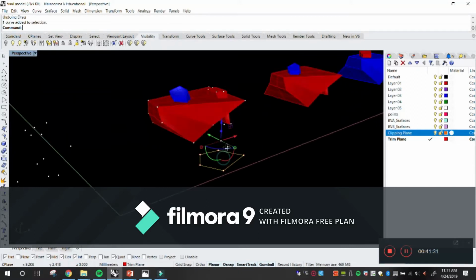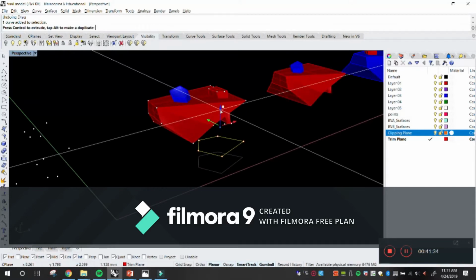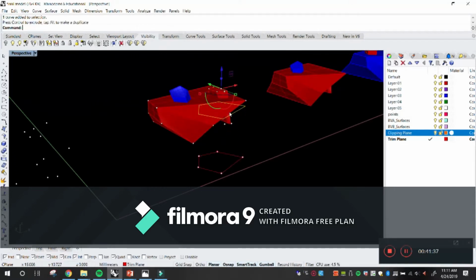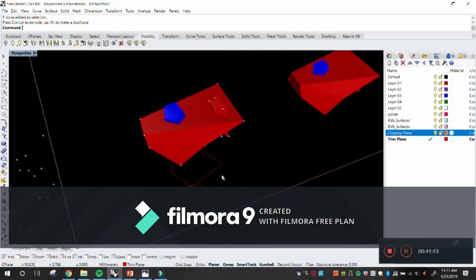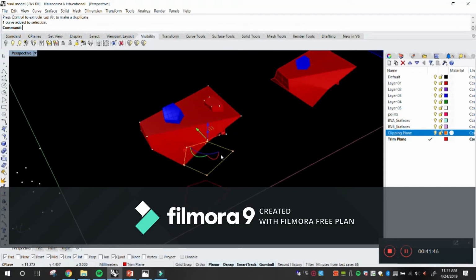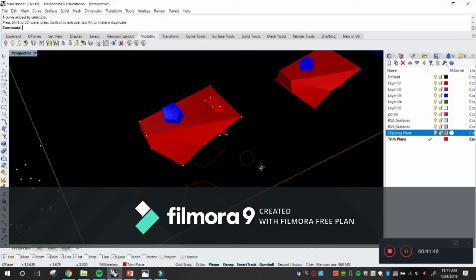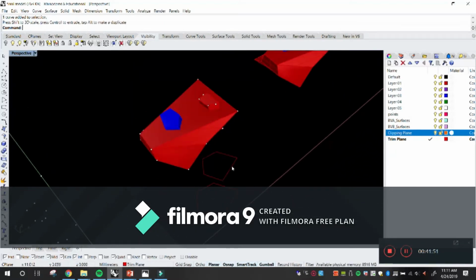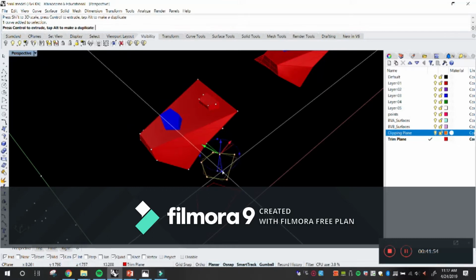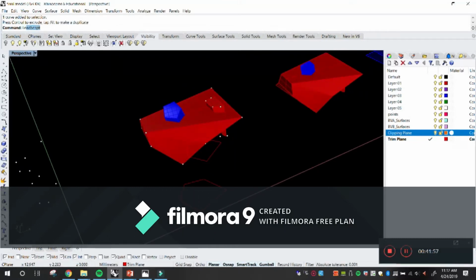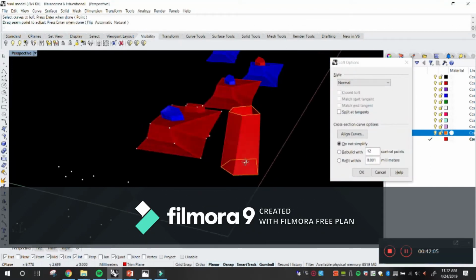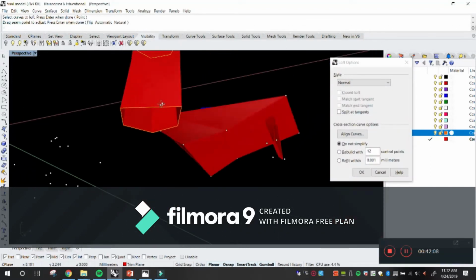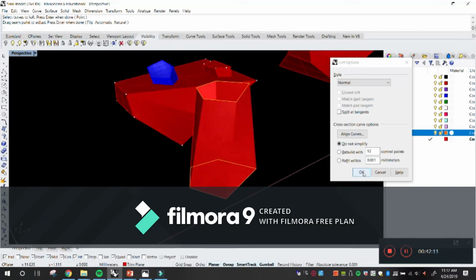You guys know how to make a quick copy, right? You select the object, hold Alt, and then you move, and you create a copy. So I created a copy of those guys right there. I can then, for example, shrink this a little bit, make it a little bit smaller, maybe even rotate it a little bit, just to give it some variety. And from there, we can work with loft. We can create that loft right there. It's giving us a direction right there, and it does that. Gives us that right there. So that's loft.